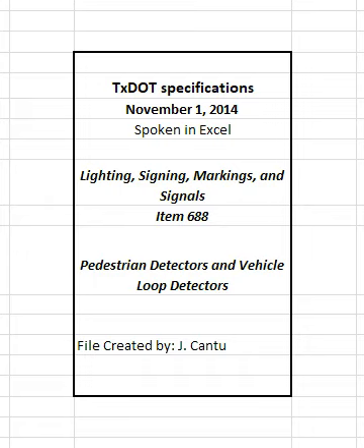When shown on the plans, use flexible vinyl or polyethylene tubing with 0.184 inches minimum inside diameter, 0.031 inches minimum wall thickness, 0.26 inches maximum outside diameter, and a smooth bore. Use tubing that does not adhere to the loop wire in any way and is capable of resisting deterioration from oils, solvents, and temperatures up to 212 degrees Fahrenheit. Use tubing that is abrasion resistant and remains flexible from 22 degrees F to 212 degrees Fahrenheit. Use orange or red tubing unless otherwise shown on the plans.